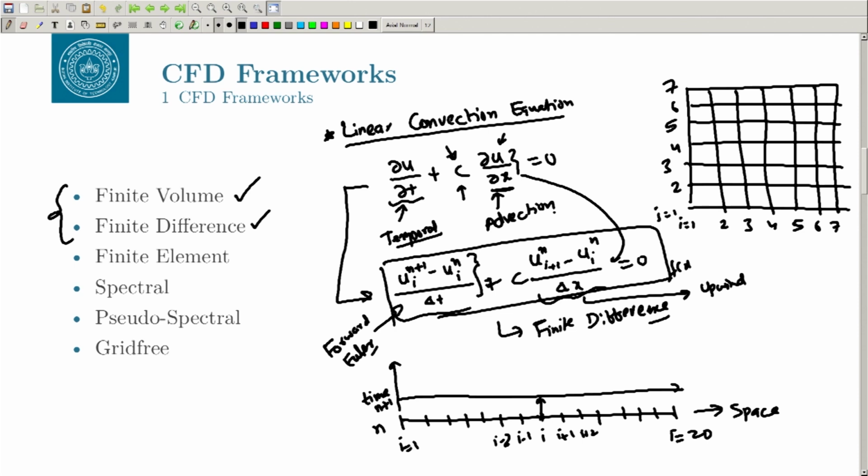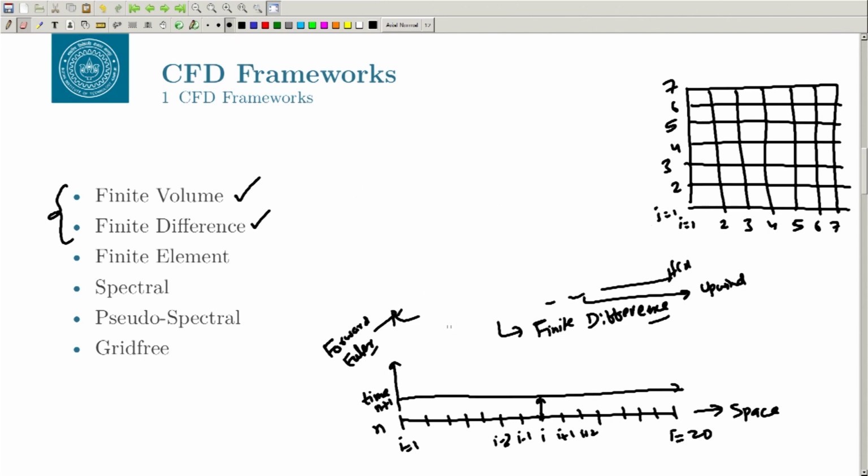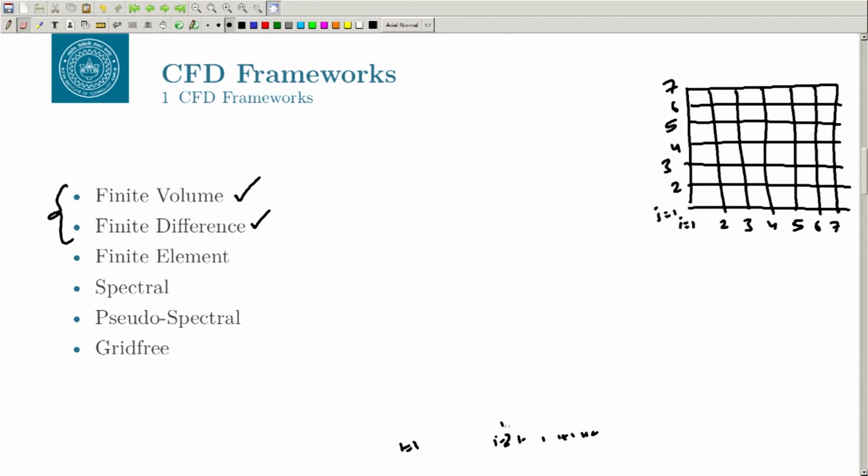So, this is how you can solve using a finite difference approach, and you can write a very nice little code in MATLAB also. Let us say if we talk about the problem that we have been discussing, okay, the lid driven cavity. So, let us think about that problem. Your governing equation would be the physical equation that you have, maybe the Navier-Stokes equations, okay, and we will look at the different forms of Navier-Stokes equations later, okay, and you discretize, you calculate the derivative in each direction, put the boundary conditions. So, what are the boundary conditions? In 3 sides we have got wall, okay. So, basically all the velocities go to 0 here, and for the top one you have the moving lid, okay, and you solve it.